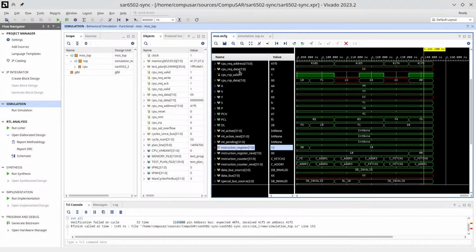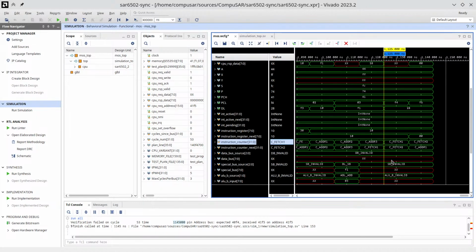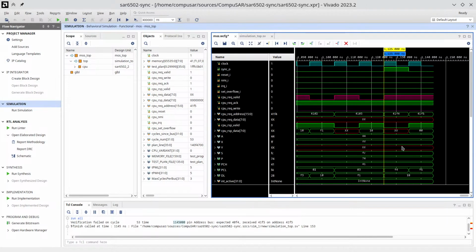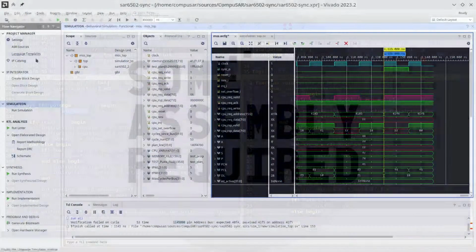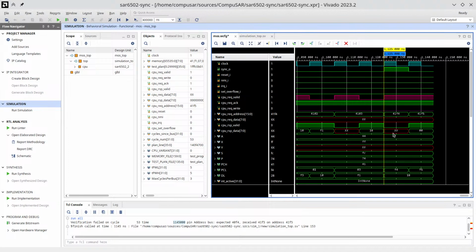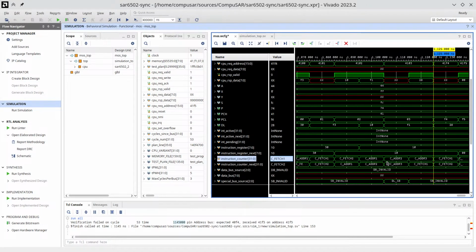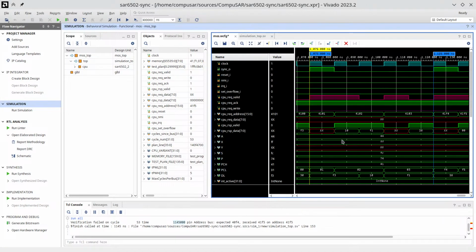The request. Okay, so let's mark where an opcode starts. So we have an opcode starting here, and this opcode is a fetch from 41F4, which is the incorrect one. Okay, so we're interested in the instruction before. So we search for the previous fetch, which is here. And that's the instruction we're after. That's the instruction we want to analyze.